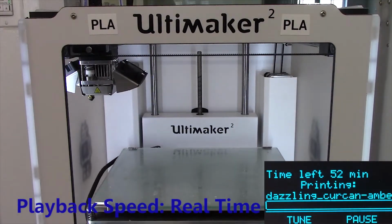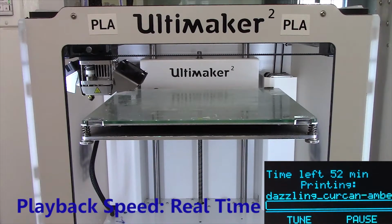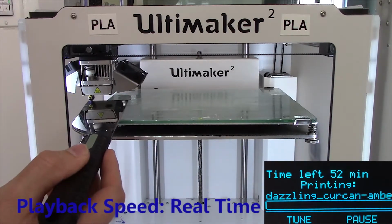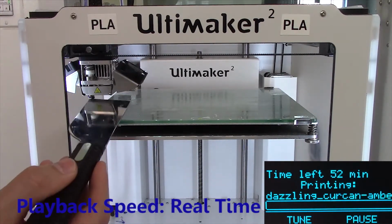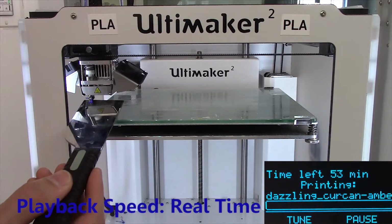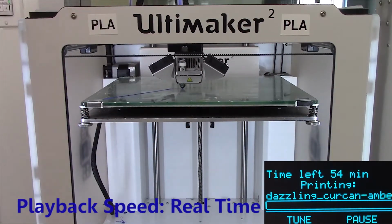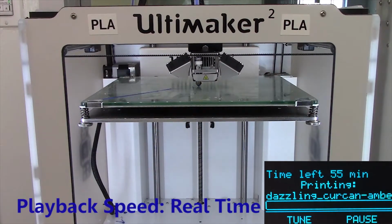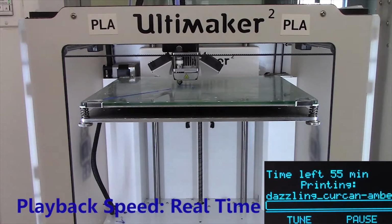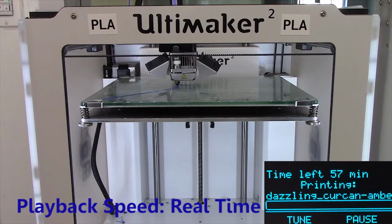And once it's ready to begin, you'll see the printer tray will rise and the filament will begin to be ejected from the hot printer nozzle. I find it helpful to use the putty knife to remove this initial filament in order to prevent the likelihood of a future clog, just to get any cold and hardened material out of the way. In the bottom right of the screen, I've included the image that is displayed on the machine, estimating the remaining print time left for each part.